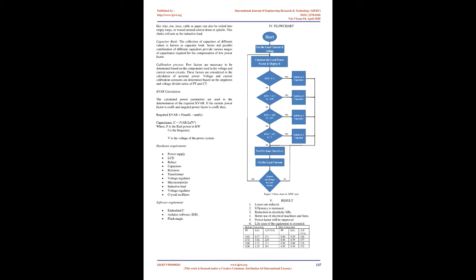3. Methodology. Figure 2, Automatic Power Factor Correction Unit. Voltage and Current Estimation Unit: Current Transformer, CT, is associated with the line, and the Potential Transformer, PT, is associated in parallel with the supply line. Comparator Unit: it takes the values of voltage and current from PT and CT respectively and gives this information to the microcontroller.